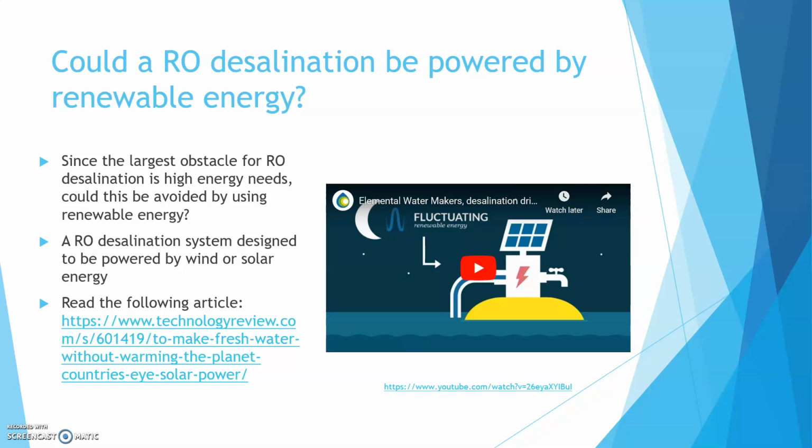A reverse osmosis system is built around its individual membrane. Each membrane is a spiral wound sheet of semi-permeable material, and the membranes are available in 2-inch, 4-inch and 8-inch diameter, with the 4 and 8-inch diameter sizes most commonly used in industry. The industry has accepted a 40-inch length as a standard size, so membranes from different manufacturers are interchangeable in equipment systems.